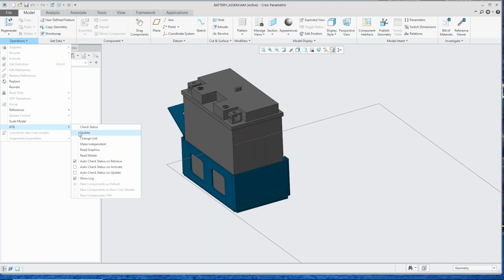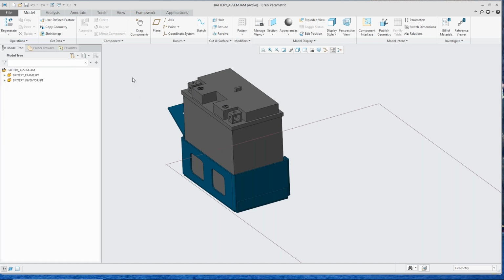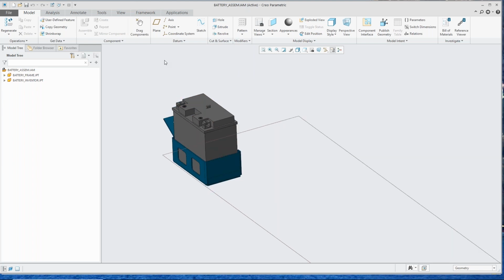So you notice we have new drag handles here. I'm going to come in and take a look at this. One of the new things that has been added in Creo 5, if we go under relief, we can go to corner relief. And under corner relief, and let's move this over to the side here, we can see that we have circular relief. So that wasn't there before. We can go in and say, let's do square relief.